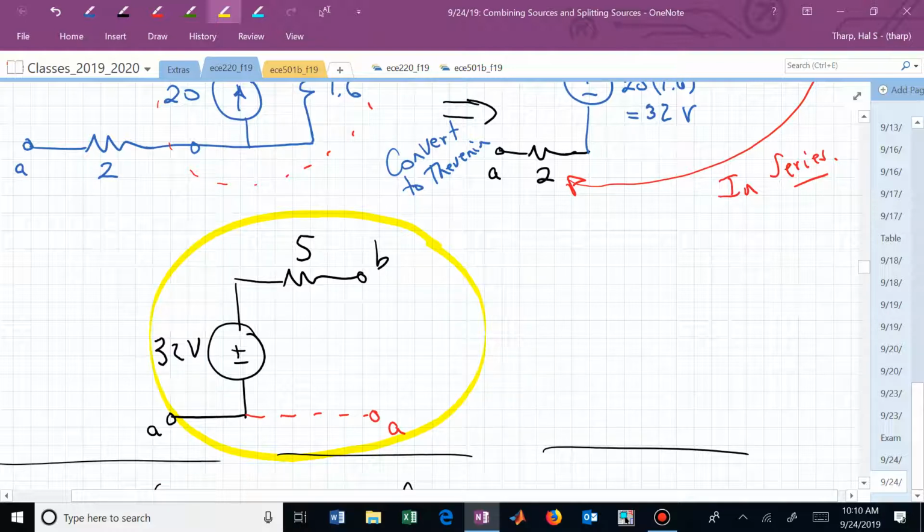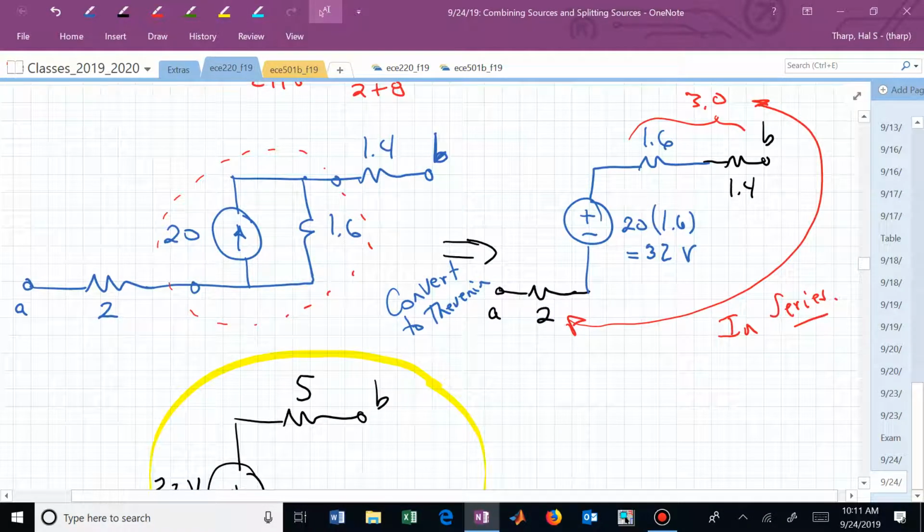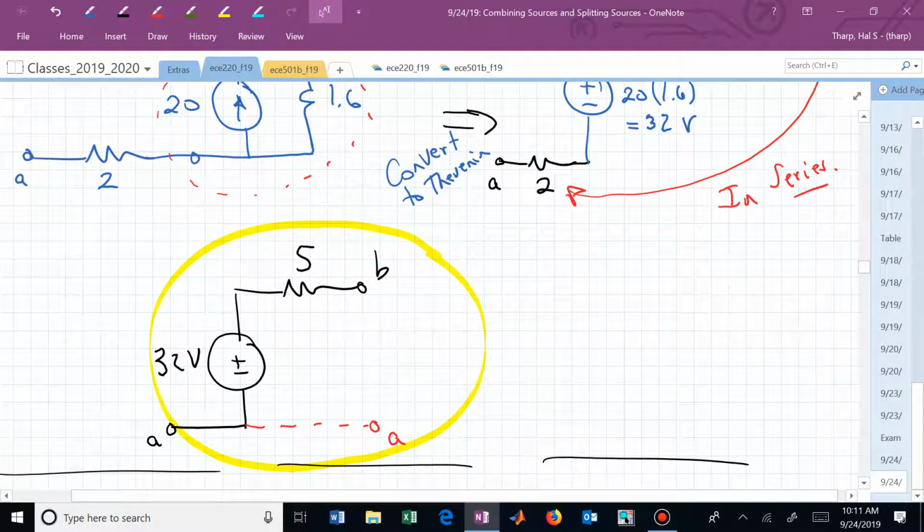That was my goal, was to find this Thevenin equivalent of that other interconnected network that we began with, which had 2 sources in it, a Norton connected and a Thevenin. We flipped them around, made the Thevenin a Norton so that they were in parallel. We combined sources. Then we needed that combination to be made into a series source, so we Theveninized that, new word, and then we combined everything in series to end up with that equivalent circuit.